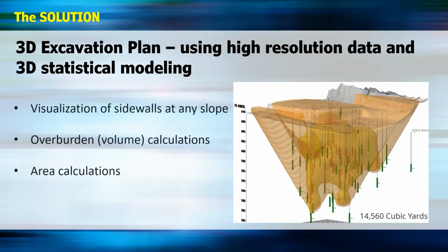But basically, these excavation plans can visualize the sidewalls at any slope desired, which allows for a really good calculation of the amount of overburden or the volume of soil you're going to remove, and then an aerial extent of the excavation and the size of that area.